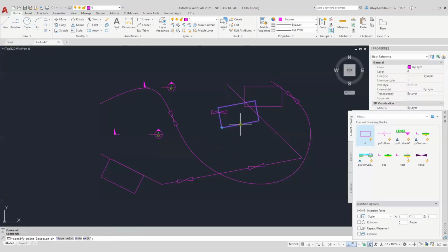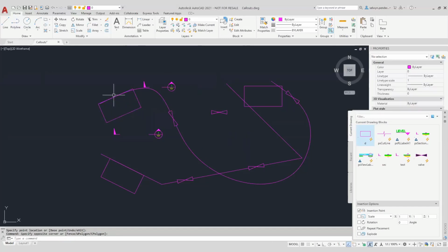Whereas if you use the grip, it will align. So there's no way of turning the grips off or the parameters off that are in your block. The only way is basically to ignore them and not change them. Great. And then when you click in your drawing, all those grips are gone, similar to AutoCAD grips. So none of that stuff prints, only the blocks that you've created.